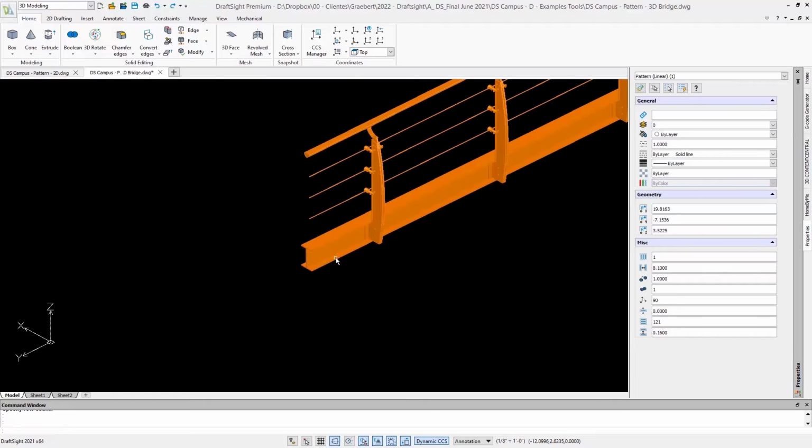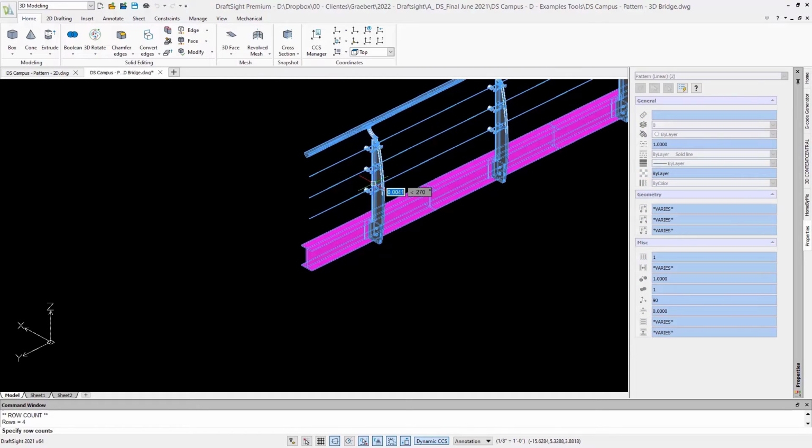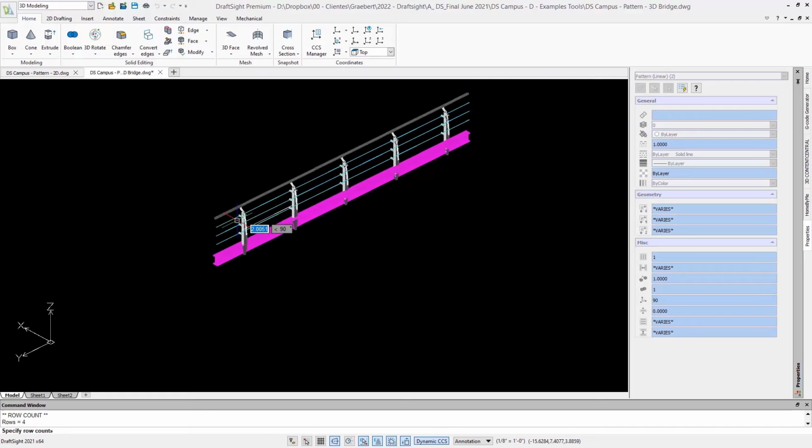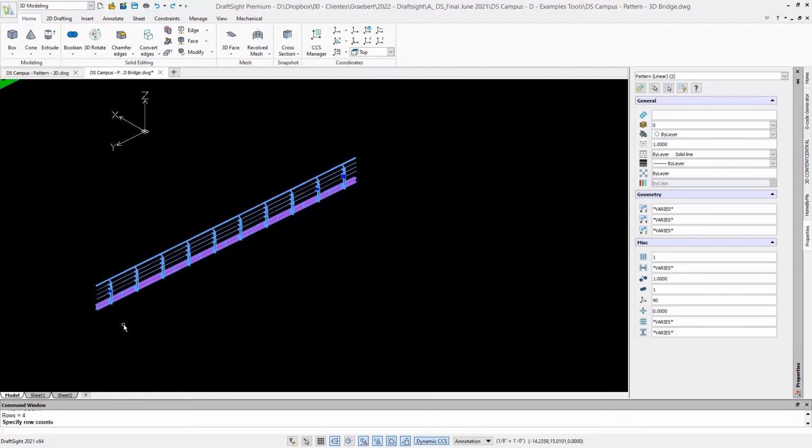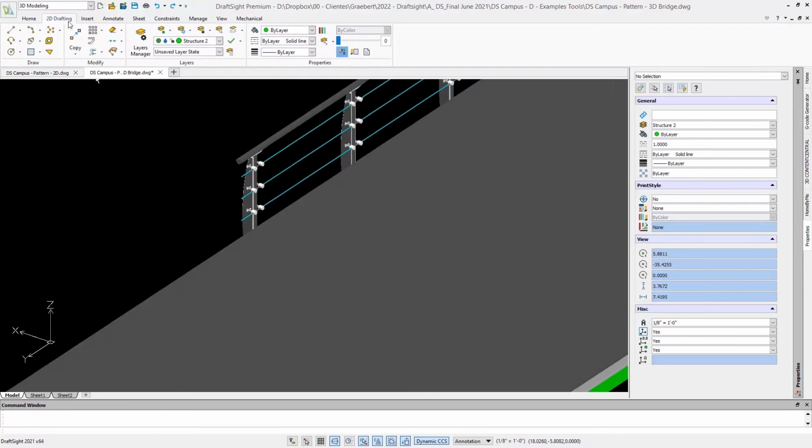So I'm going to just go straight into the railing. I'm going to select it. And by simply selecting the points, I can extend that. So in this case, I've extended it to cover the entire face of the model. I can also configure if I'd like to run a more customized pattern.